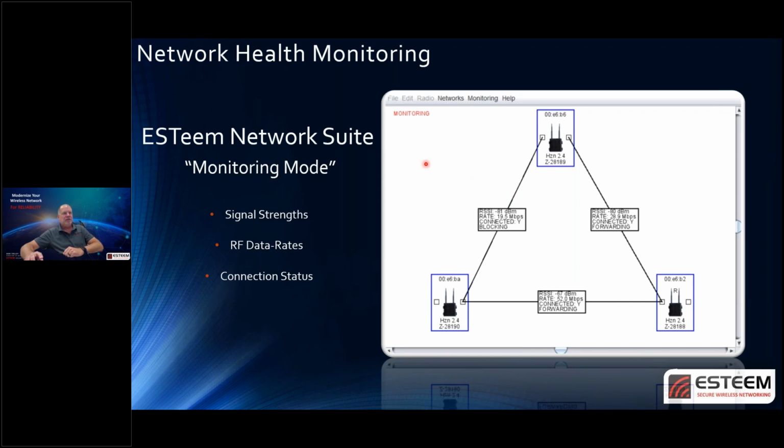And so you can go and look at this and see exactly what's happening. Think about this three-dimensionally. If we start to see, maybe we've got tree growth coming up, now we can look at this and start to look at some trending. Maybe our signal strength is dropping because of those trees. Well, we may want to go in and change that so that maybe our primary pathway is now going through that repeater instead of direct. Again, you can do it right from the same utility, just by altering those path lengths.